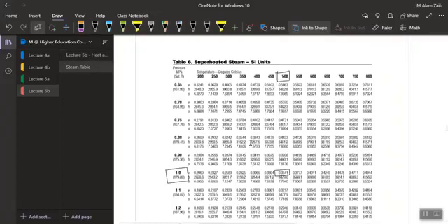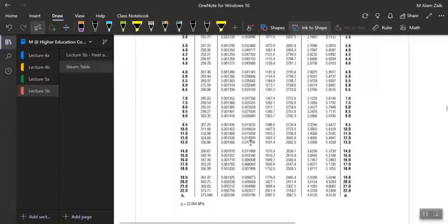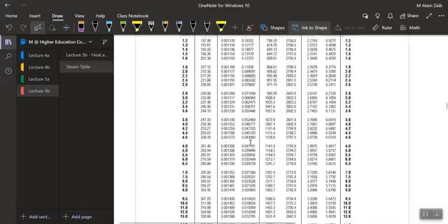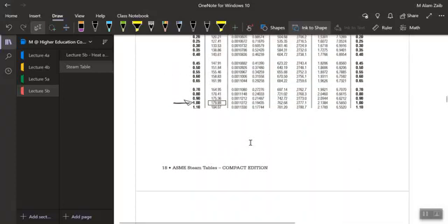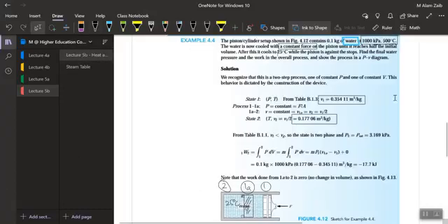So let's go to the same saturated table, the saturated water table, and check the condition of the steam. At 1 megapascal, the condition is 0.177 something. So if you can imagine, 0.177 is less than Vg and greater than Vf somewhere. That means we are inside the vapor dome. So 0.17706 is inside the vapor dome.